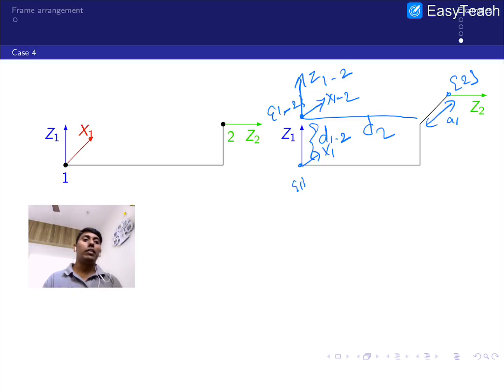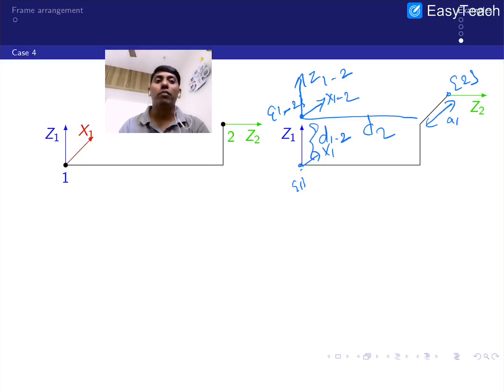Like that we can incorporate it, but you can already see the limitation of the DH parameters. Although you physically have two frames, you are introducing a virtual frame, right? If you are not introducing a virtual frame, you cannot accommodate it as per the general Denavit-Hartenberg convention. Otherwise you have to assume that this is the x-axis, or make some arrangement, but even if you make it, the physical interpretation is not coming, right? So that is the main case.